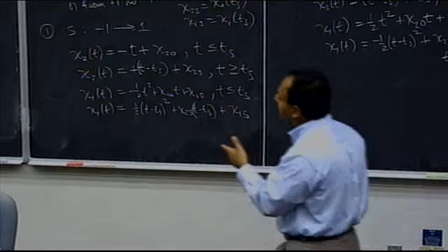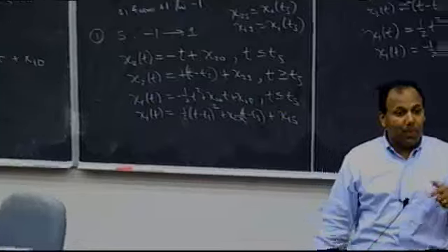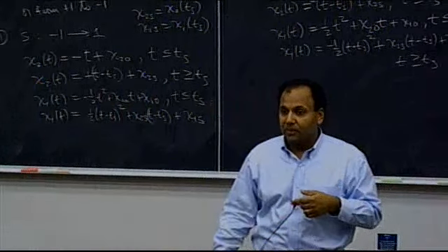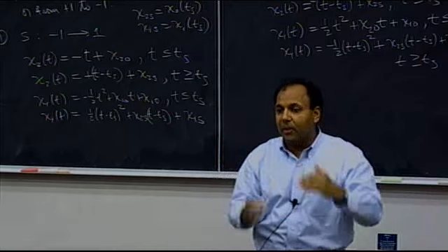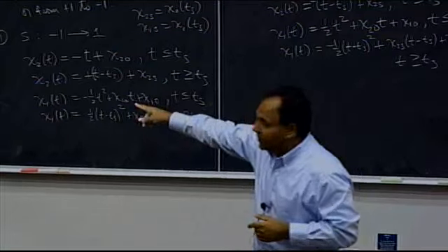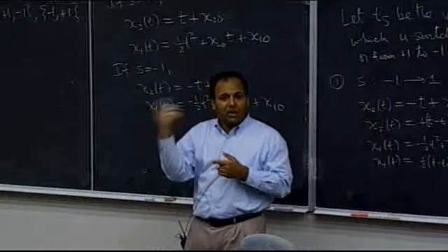Now you can imagine that this is a double integrator plant. If you have a triple integrator plant, then you're potentially going to get more than one switch, because for every integrator that you add into the system, you add one more polynomial degree to your solution. Here we've got a quadratic. If I had a triple integrator, I'm going to have a cubic.